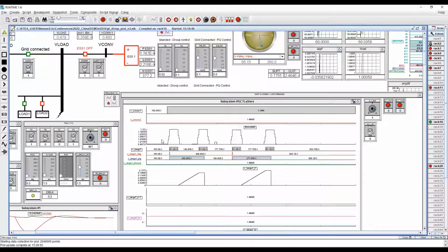So the controllable source generates a series of voltage disturbances. Each of them has a duration less than the required minimum ride-through time. The duration between any two consecutive disturbances is made less than the required minimum time between successive disturbance sets.